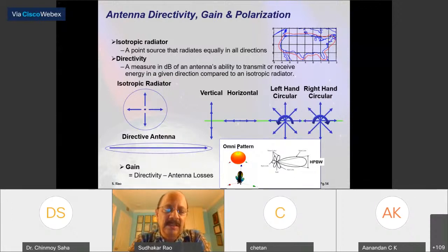So I assume that you have a certain tapered distribution, and ask how much directivity you can get in the far field. That's basically directivity. Then you have to account for all antenna losses. So there could be reflector RMS, the feed losses, polarizers, filters, diplexers, the transitions, etc. All these things need to be accounted for, and also thermal effects.